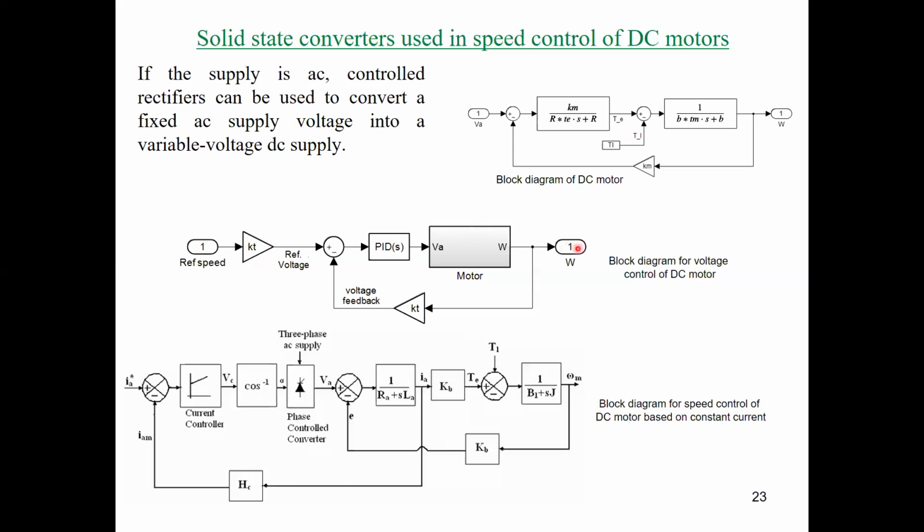Simply, we have the speed of the machine. We will measure the machine speed, using the transducer ratio in order to convert speed to a voltage signal. We will also have the reference speed, which is the required speed, and we will multiply it with the same ratio of the speed transducer to get the corresponding reference voltage.